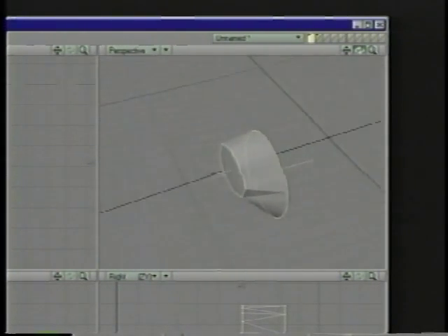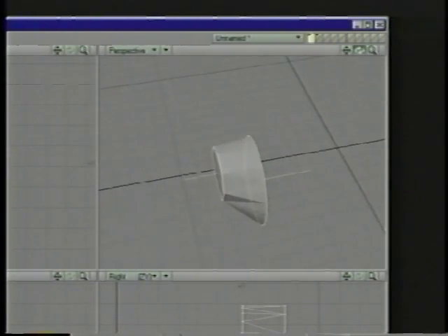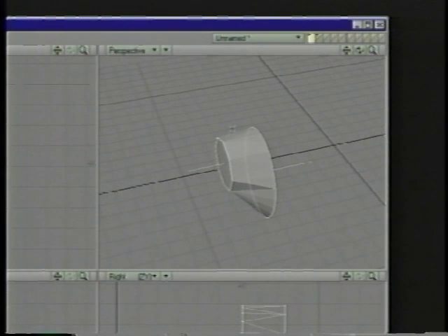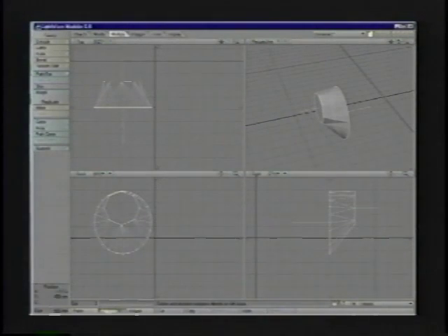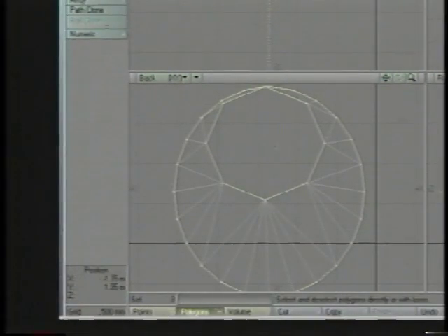This is a very handy little tool if you have geometry that you need to join together with a surface, but you don't want to go in and by hand create polygons by selecting the points and making polygons. Modeler will go in and do it for you. You'll also notice that these are all tripled, and so it keeps you in good shape as far as creating planar polygons so you don't get any non-planar trouble. So that is a skin, and that's a cool way to bridge between 2 polygons, and there's another way to do that with the morph. Let's take a look at that.